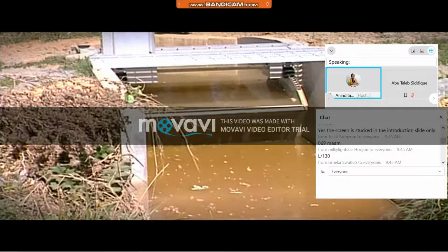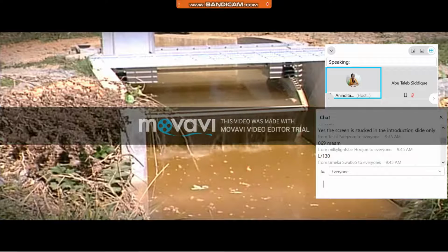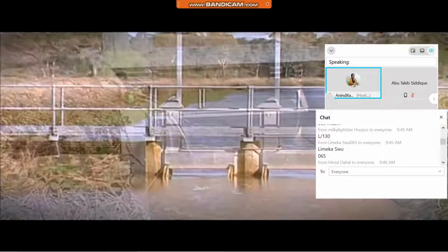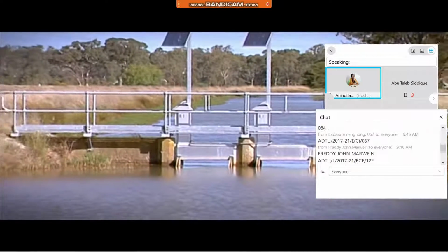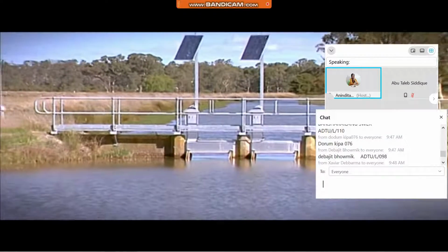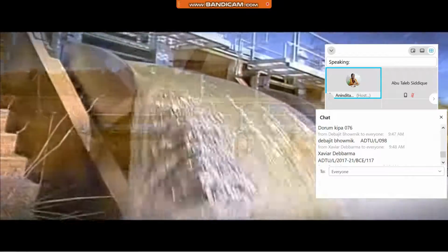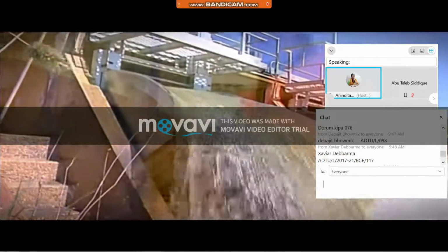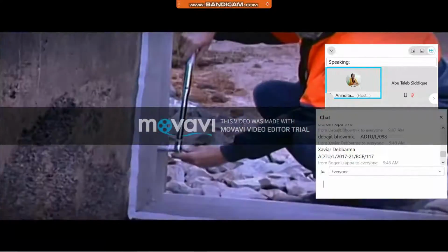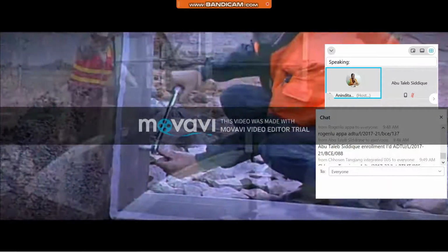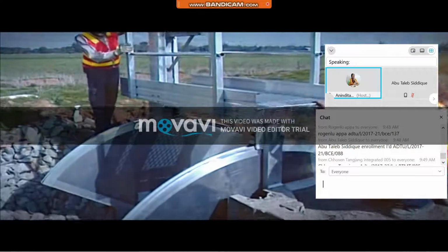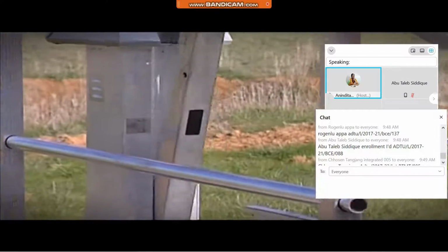To date, TCC is achieving efficiency improvements in the order of 20%, which in turn is generating significant quantities of new water for urban, environmental, or further irrigation uses. Total channel control involves retrofitting Rubicon's flume gates to existing regulating structures, enabling accurate flow and water level measurement at each structure, as well as optimal control.